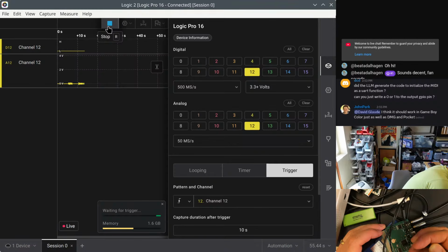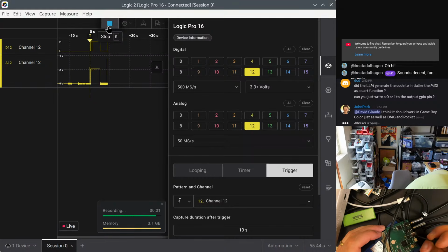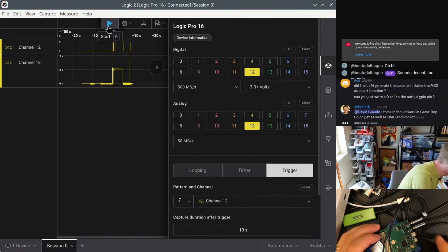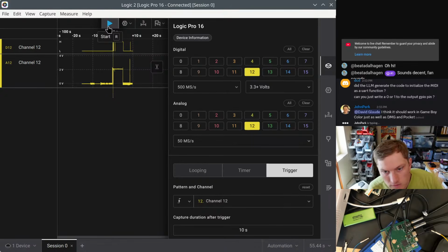This side of the resistor is low. This side of the resistor is high. So something is keeping it low. I wonder if it's possible my opto isolator is backwards. Like I have it oriented wrong. I wonder if that would do it.